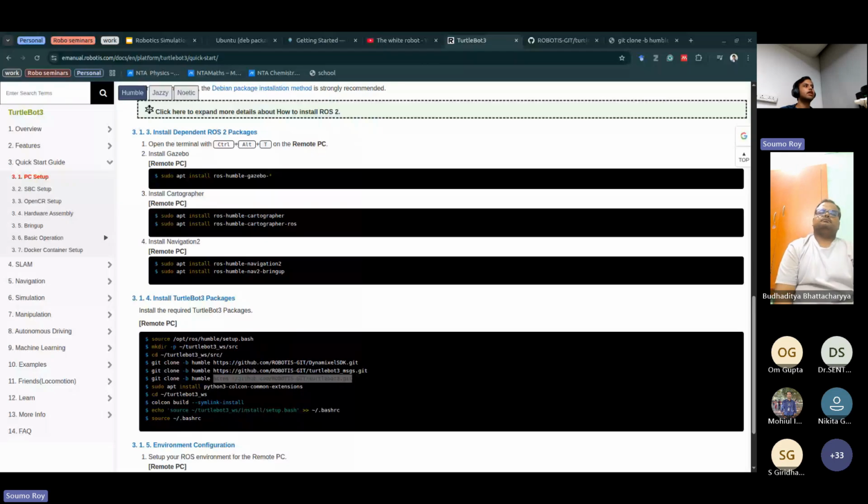We connect to the same Wi-Fi, we know the IP address of the Raspberry Pi, and we can ping it and SSH to log in. Now I have access to all the data of this robot. There is no security. Imagine you have to deploy this robot at the border for surveillance or security purposes. I can easily log into the robot, see all the topics, and see all the sensor data. So it's a security risk. To have a centralized system of safety and security and better communication, we moved on to ROS2.